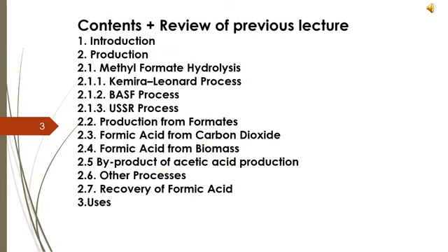As we have said, we have fed all the methyl formate which was produced from the methyl formate column into C, and along with that the recycled materials we also have fed into D. So from C, methyl formate and any recycled material like methanol or water we have fed into D.